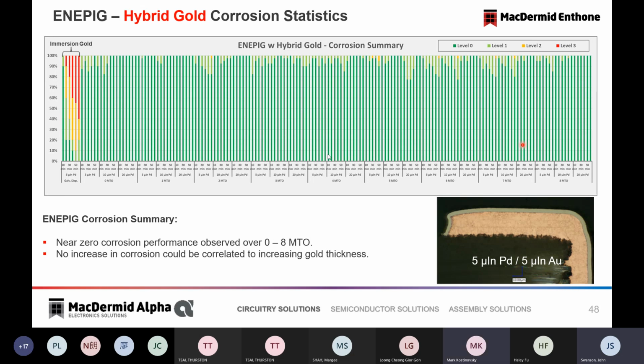Okay, and I don't know if I'm asking too many questions, but the reducing agent for gold is also commonly hypophosphite, or am I asking for a trade secret? Yeah, no, you're not asking for a trade secret. It's overwhelmingly from all vendors that hypophosphite is the reducing agent. The differentiation among vendors really comes into relationship with stabilizers and some stability agents. All right, so the reducing agent is quite common.